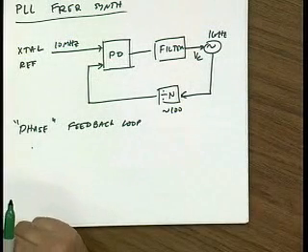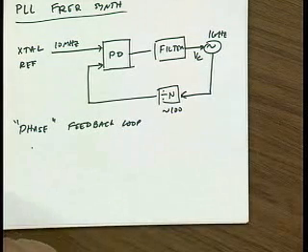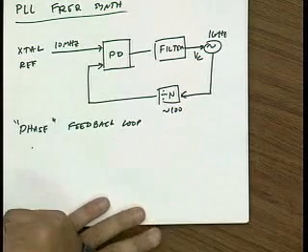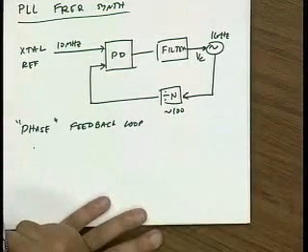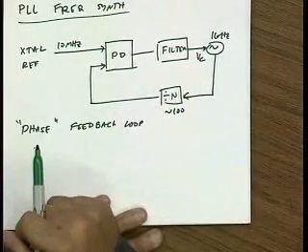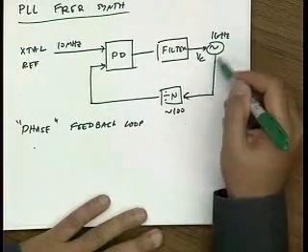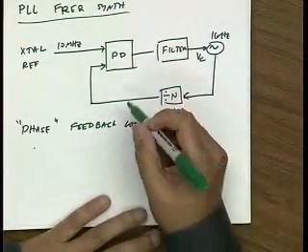Okay. So this is a highly nonlinear feedback loop. We're going to linearize it in order to analyze it. You can also use tools like MATLAB or Verilog-A to analyze these kinds of circuits. It's what we call a mixed signal circuit because it involves a high frequency oscillator. It involves dividers, which tend to be digital circuits.